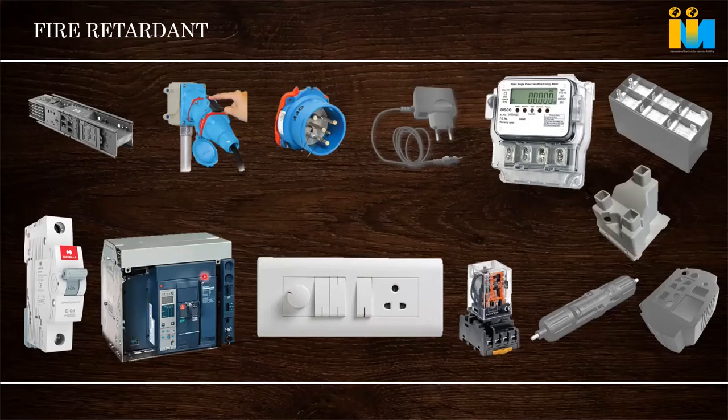And then comes the ACB, air circuit breaker. This is the first and foremost safety device when we are entering any factory or where a huge amount of current is being used. The body, the outer area of this product, is made of polycarbonate. Most probably higher grade products are made of 10% glass filled polycarbonate, fire retardant grade, V0 fire retardant grades.